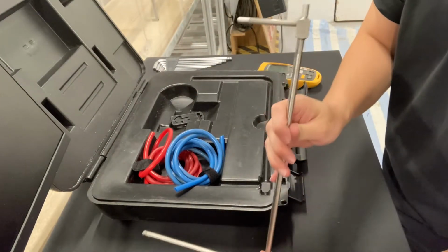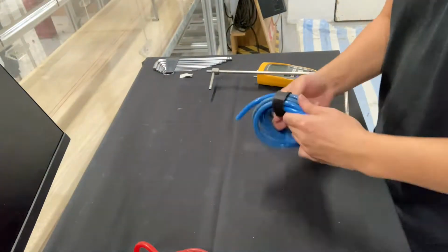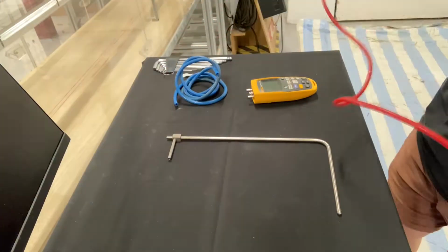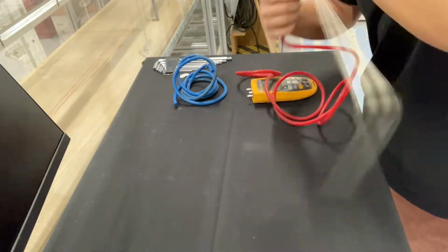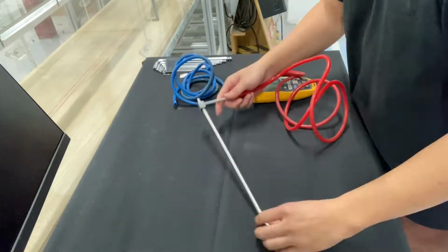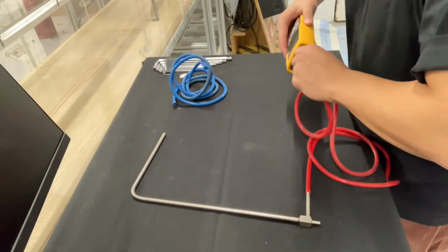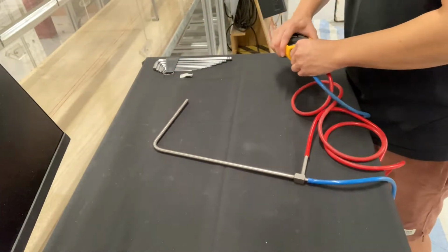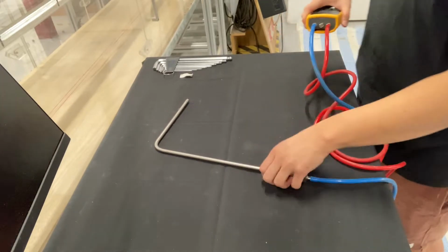Now remember, this is an open circuit wind tunnel, so the setting could be slightly different each time that we do the tests. So what I'm doing right now is putting together the pitot tube that will help us measure the free stream velocity directly. As you can see, the pitot tube connects to a digital airflow meter, where the blue hose connects the total pressure and the red hose connects the static pressure.